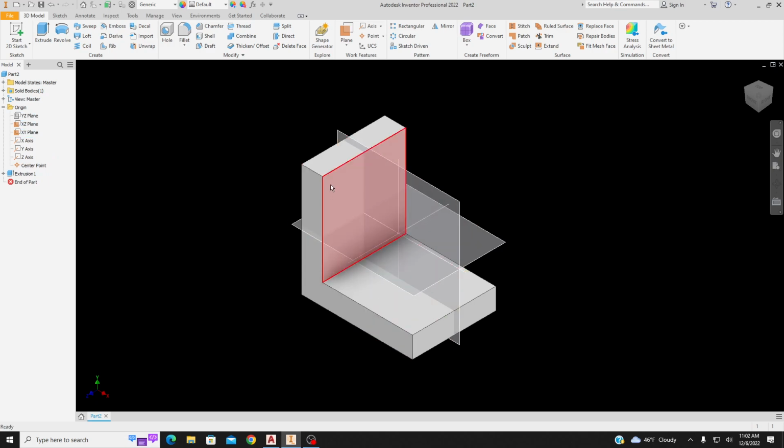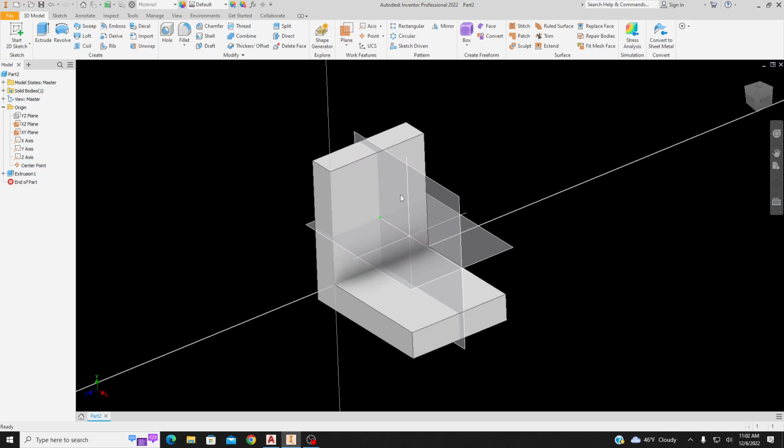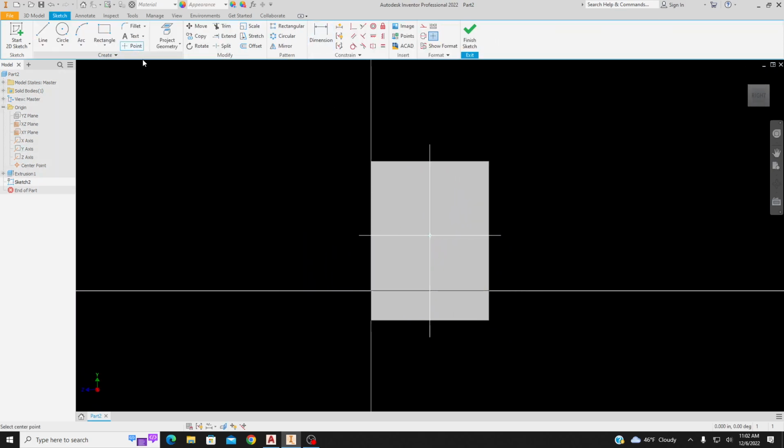What we want to do is put one of our 4 holes right in this front face of our angle bracket. So we'll click on the surface and then we'll click on create sketch. And we're just going to use the point tool. Really anywhere, somewhere in this lower left hand corner is a good spot. And then we're going to dimension where that goes.